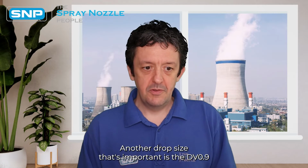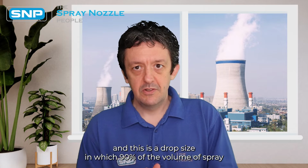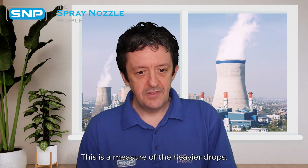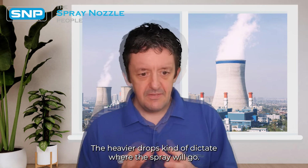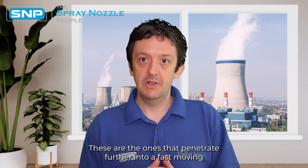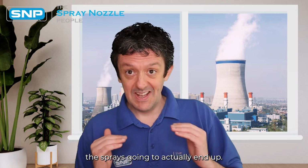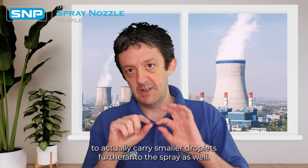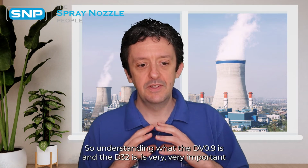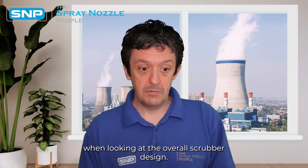But another drop size that's important is the DV0.9. Now, this is the drop size which 90% of the volume of the spray is made up of drops smaller than this drop size. So this is a measure of the heavier drops. The heavier drops kind of dictate where the spray will go. These are the ones that will penetrate further into a fast-moving gas flow. This is the drop size we need to understand to work out where the spray is going to actually end up. Those bigger droplets also serve to actually carry smaller droplets further into the spray as well. So understanding what the DV0.9 is and the D32 is very important when considering overall scrubber design.